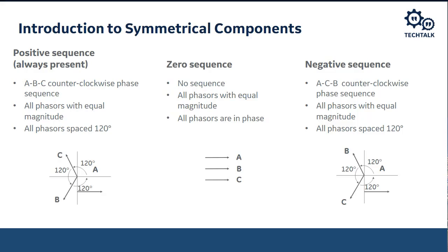If you ever do your calculations and your positive sequence components are zero while your other components are non-zero, you've made a gross error somewhere. If you're ever looking at metering quantities and your positive sequence quantities are zero and your other quantities are non-zero, then you've probably made a gross wiring error somewhere.